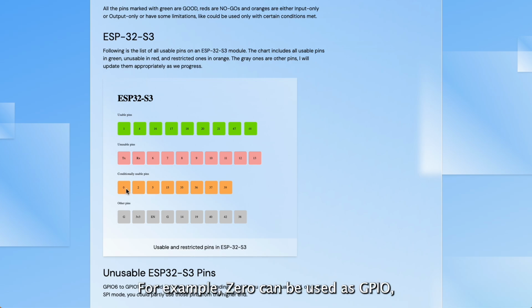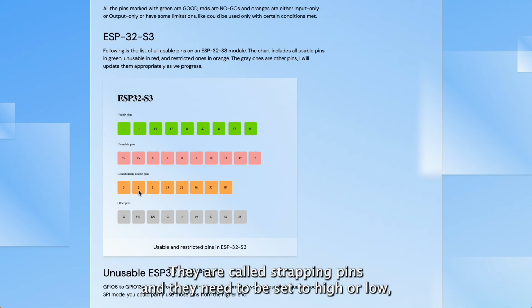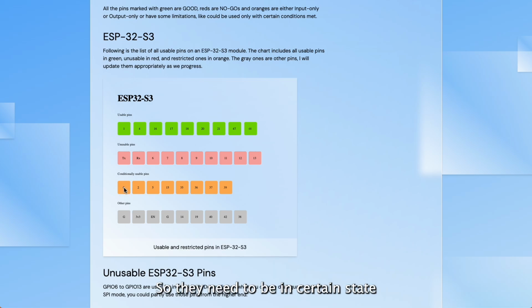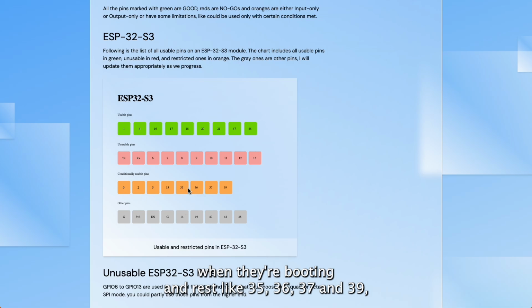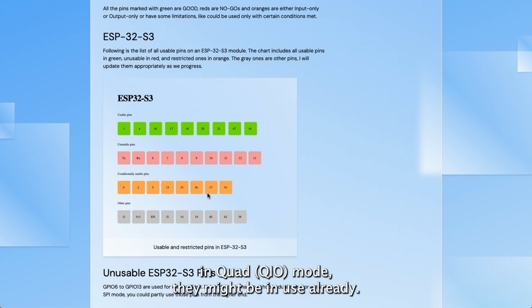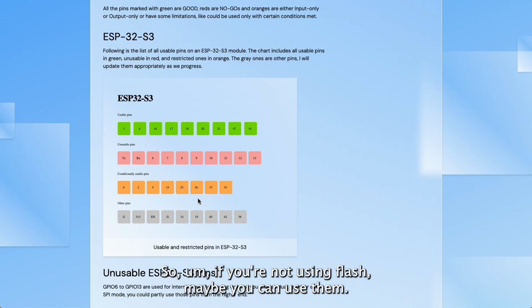For example, 0 can be used as GPIO, but the problem is 0, 2 and 5, they are called strapping pins, and they need to be set to high or low depending on how you want to boot your microcontroller. So they need to be in a certain state when they're booting, and the rest like 35, 36, 37, 39, they probably would be used for PSRAM, or if you're using the flash memory in octa mode, they might be in use already. So if you're not using flash, maybe you can use them.